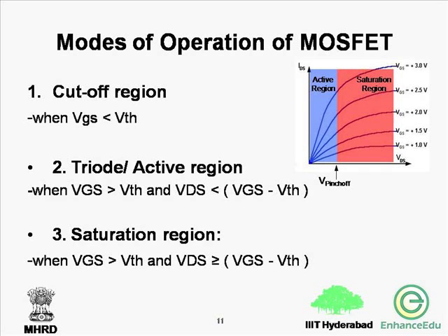These characteristics are also very clear with the IDS versus the VGS curve, which is on the right hand side. Different regions can be shown in it as well. That is, if the voltage VGS is below the threshold, where the graph is almost constant, it is the pinch-off region. Whenever the curve starts becoming linear, it enters into the active region, and later the device moves into the saturation region. So these are the different characteristics with which the MOSFET functioning in three regions can be shown.